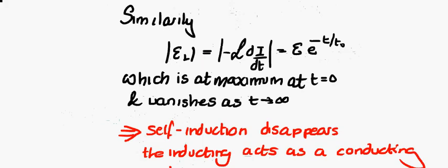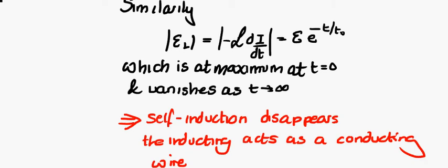Instead of considering in terms of current, we could view it in terms of change of our net effect EMF, and we can see that the reason for this is our EMF would vary with an exponential decay because of the exponential form of the inductance. So what we could comment from a physical point of view is that self-induction vanishes with time towards our approximation of a steady system.